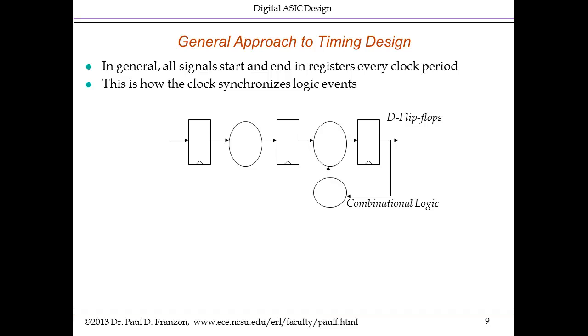So in the revision module, you saw diagrams like this. I just want to remind you about the general approach to timing design. Remember, the way in which logic works for edge-triggered flip-flops is on each positive edge of the flip-flop, the flip-flop outputs become equal to the flip-flop inputs simultaneously on all the registers in the design. Between the edges, the data propagates through the logic to work out what to present to the flip-flops at the start of the next clock cycle.